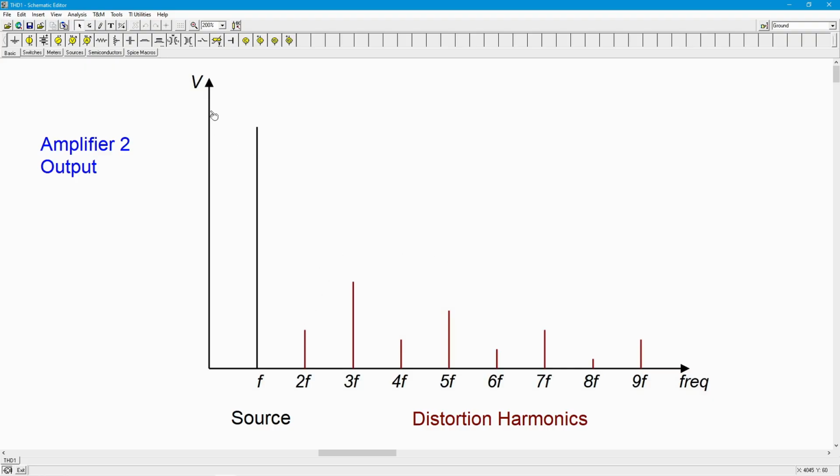So if you had, like I said, a C weighting filter, that would come out and drop out here. And now you could compare two amplifiers, one that had a wildly different sort of fingerprint than another, but they're going to work out the same in this particular measurement. The other thing is the noise. If you have a wide bandwidth amplifier and you don't have the weighting filter on there, then guess what? All of that noise gets thrown in and it makes that amplifier look worse. And it's only because it has a wider bandwidth, but you can't even really hear the wider bandwidth. So it's kind of being penalized unfairly.